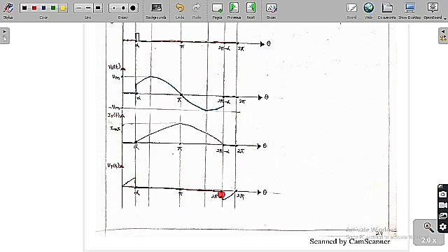From alpha to 2 pi minus alpha the thyristor is on, so it is going to become like a short circuit, meaning the voltage across it is 0. Whereas from 2 pi minus alpha to 2 pi, we have said that it is going to act like an open circuit. So the voltage across the thyristor is equal to the source voltage, again following the source voltage. So this is the diagram we are going to get for the output voltage, output current and the voltage across the thyristor.